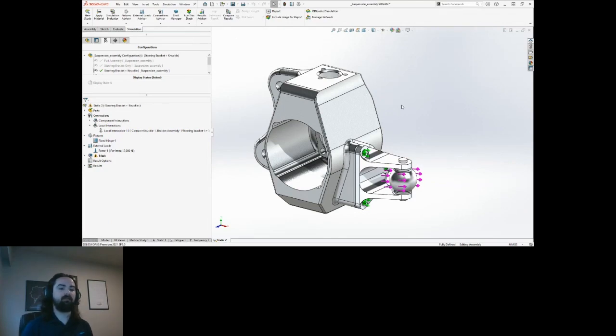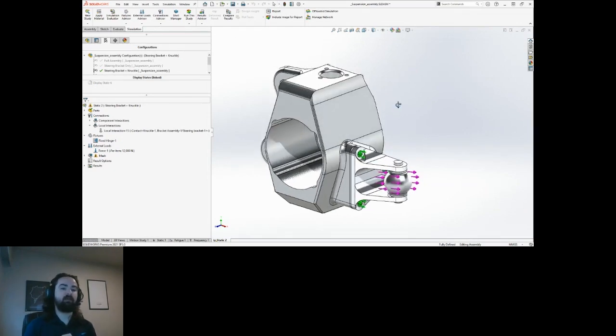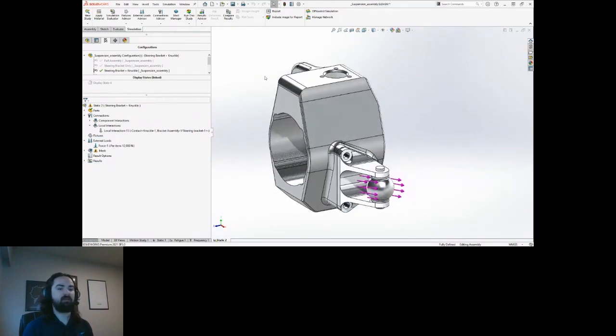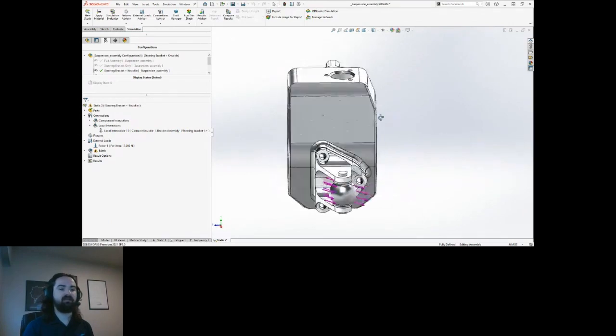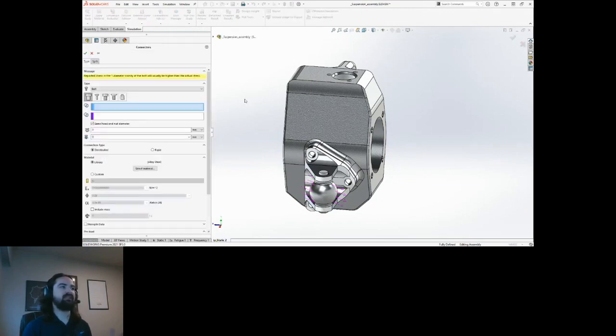Next up, I'd like to properly represent the bolts in the assembly, including preload this time. I'll start by deleting the hinge fixture since we won't need it anymore. Just like with the slider fixture, we're going to be replacing it with these connectors. And so now the best way to represent the bolts isn't actually by including the components in the study, but instead to represent the bolts using bolt connectors. So I'll go to my connections, select the bolt connector type, and then basically I need to choose what type of bolt or screw I want to use.